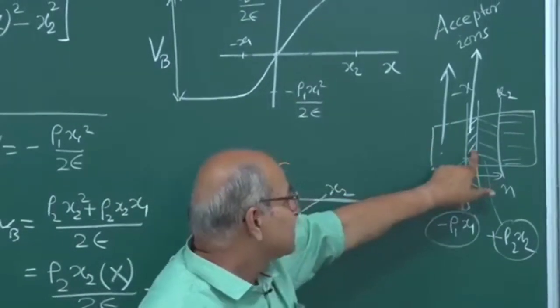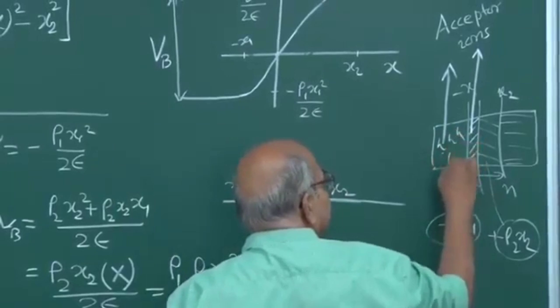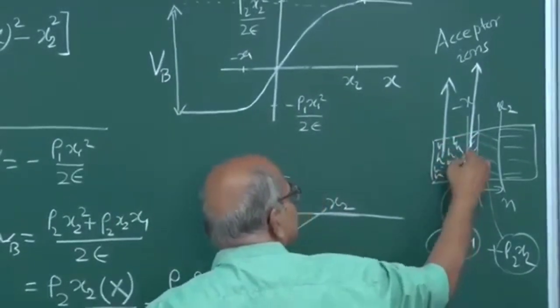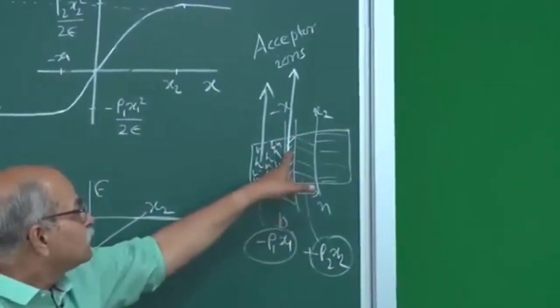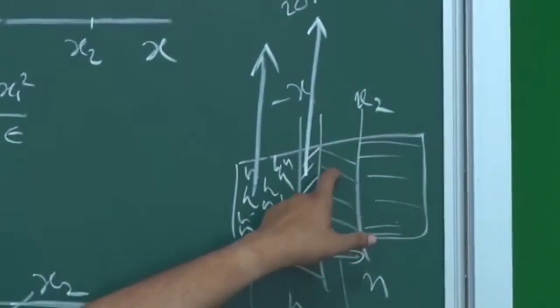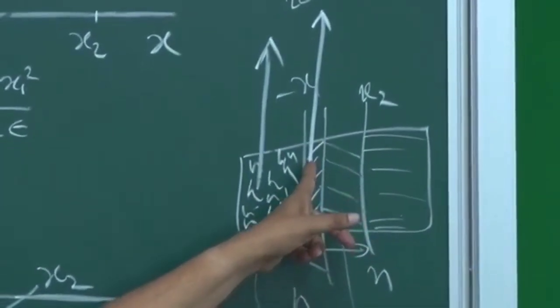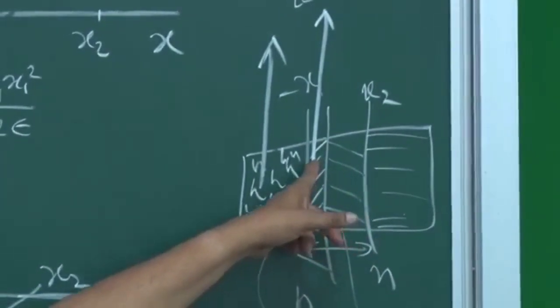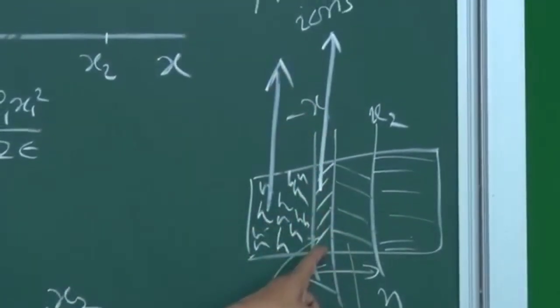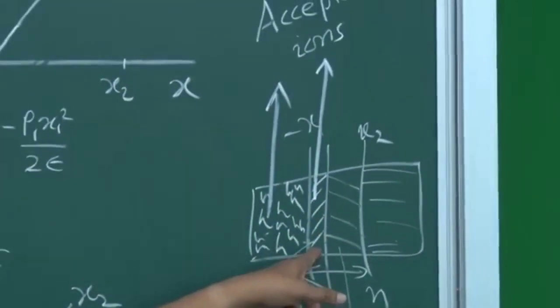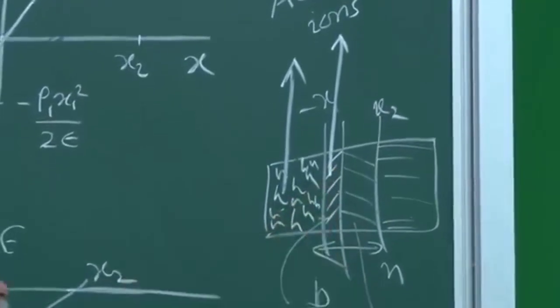So same thing is here. Here holes are still there, and therefore there is a charge neutrality. And here the holes have migrated to this side and recombined with electrons, or electrons have come here and recombined. This charge carrier has gone. So those ions which are there, those will still remain there. The hole has moved and recombined and has gone away. Therefore, you have this negative charge.